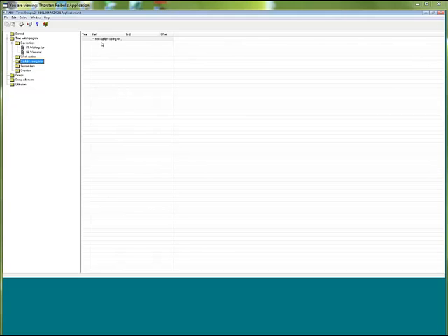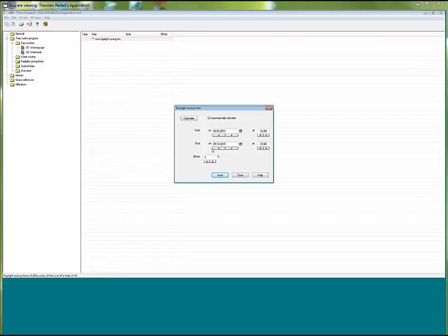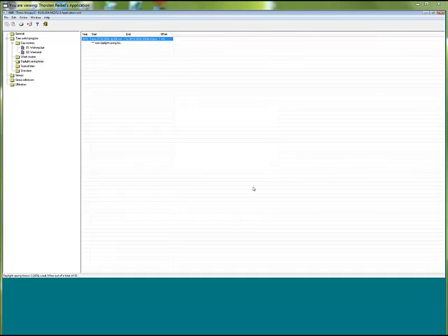Daylight saving time, something I should mention as well. You can create here, if you have the internal clock, for example, there is no, let me say, possibility normally to have summer and winter time available. You have to say to this device how to do this. So you say for each year what happens with the daylight saving time if you have it in your country. Yeah. So you can go to the next day, and then maybe it's the same. You can calculate this automatically, and then you assign this here. Yeah, and you insert this, for example. If you have an external clock, like our weather station or weather unit, which can send automatically the right time thanks to GPS signal, you don't need this, of course.